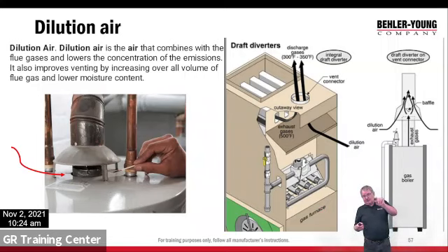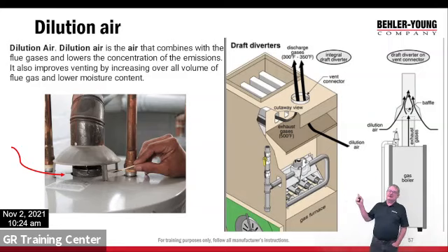That pipe right there sticking out the top of the water, that's where the flue gases are coming up. Yeah, because it's drawing basement air in. And like you see in the picture, if you took a match, it's one of the ways we check for a draft. You take a match, put it out where it's still smoking, and it should suck that smoke right up that draft diverter.